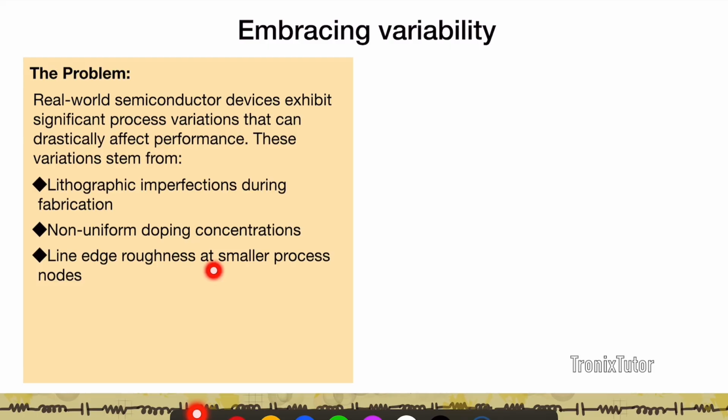Line edge roughness, especially as you scale down features, the gate, the contacts, etc., can start having line edge roughness, which means the CD is changing, which impacts either the capacitance or the contact resistance. You also have what are known as random dopant fluctuations, where the dopants under the gate change, and that causes changes in the VT of the transistor.